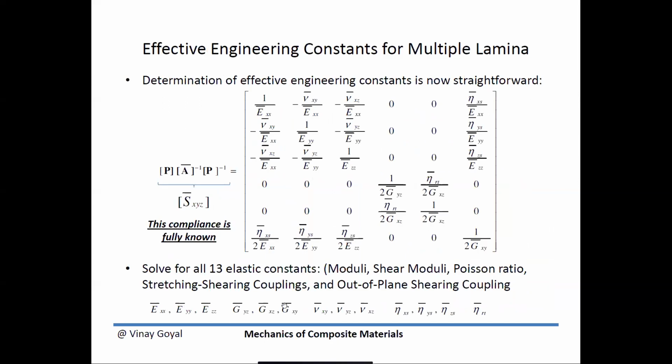So once I have these coefficients, what I've done is really found the properties without having to do any testing, which can be verified to do very well against testing as well. So this can also be used to do some spot check of your test, to make sure that everything is in good shape from the testing perspective as well. But the two fundamental benefits are you can simplify the finite element modeling, and you can get properties in advance of any testing.